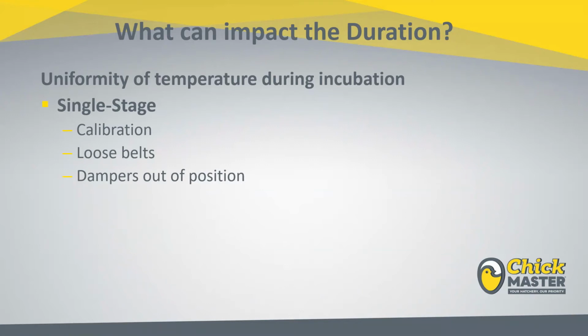And a lot of times I find that those are either not calibrated correctly, or they are out of sync, and you'll allow higher volumes of fresh air to dump into certain zones and not others. And that within itself causes the individual zones to operate inconsistently, and that can create that poor uniformity in temperature.